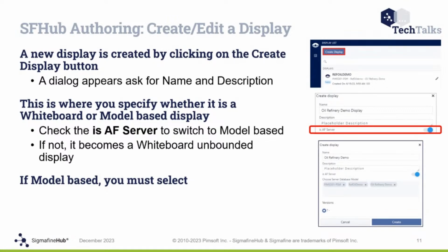You can save it; it becomes a display. But if the model already exists in your AF database, then it's a model bound display. Then you have to select the right database server, the right database itself, and the right model in that database, in that order.